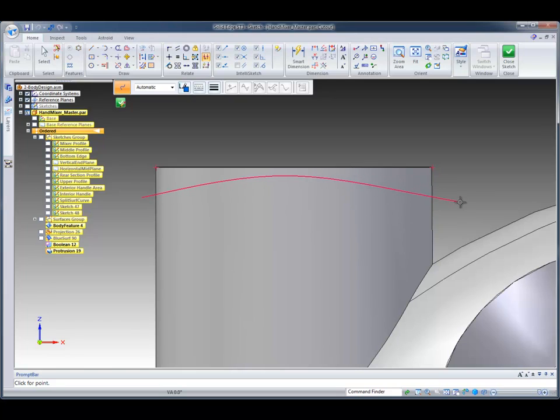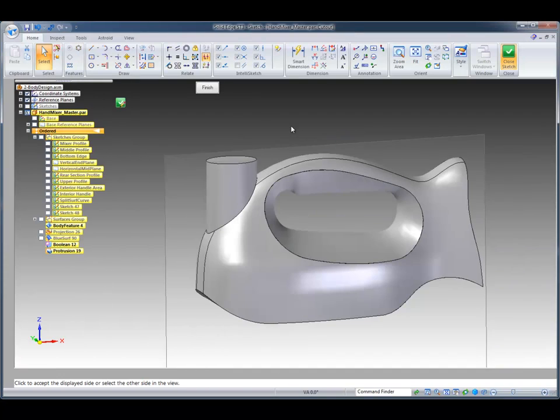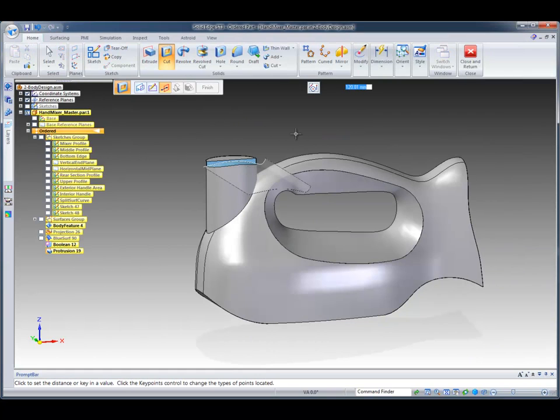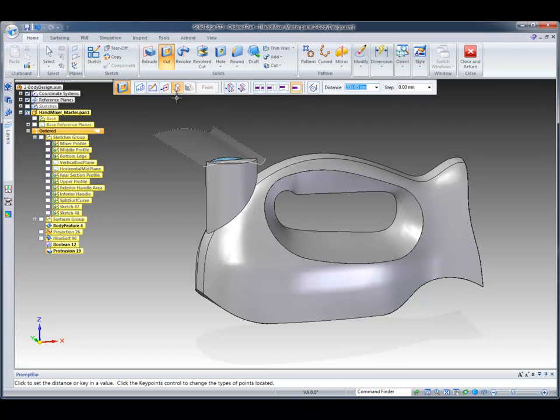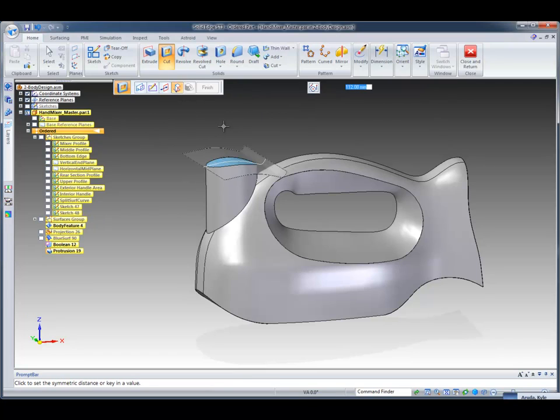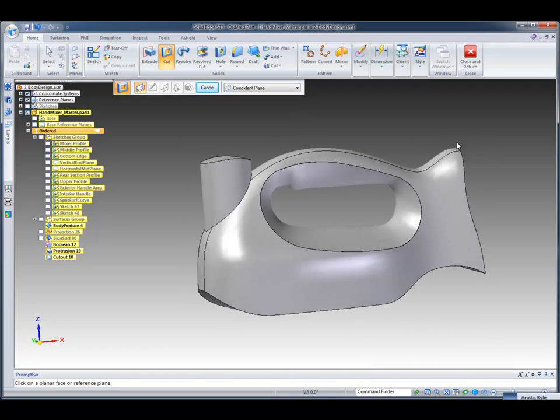And then I'm going to turn it up because it is an open profile, and in Solid Edge when you have an open profile it's going to cut across the model. And then once we build this curve, if we need to make any kind of an adjustment, we can. If we want to change the shape of it, that's all possible when you build a curve. Just have to manipulate it a little bit. But when we close the sketch, we'll have the option to remove the material, in this case from the top side, and we'll want to go in both directions. And so let's go ahead and select that and remove that material. And it kind of gives you an idea of what that's going to look like.